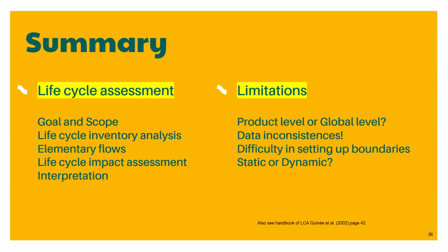And it is also important to understand the limitations of the life cycle assessment tool. For example, if the product is manufactured in different locations, it can be challenging to map out the entire life cycle. Data inconsistency is also very common in life cycle assessment. And again, setting boundary conditions such as cradle to grave and cradle to gate is also very difficult and requires careful consideration.